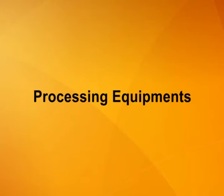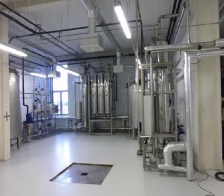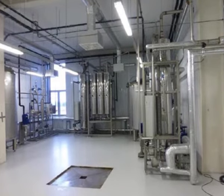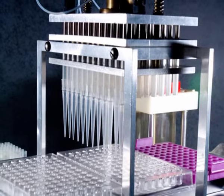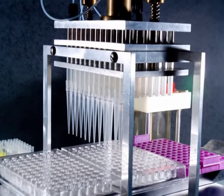Processing equipments. The most economical, simplest and efficient equipment capable of producing a product within the proposed specifications is used. The size of the equipment should be such that the experimental trials run are relevant to the production size batches. If the equipment is too small, the processes developed will not scale up, whereas if the equipment is too big, then wastage of the expensive active ingredients will happen.